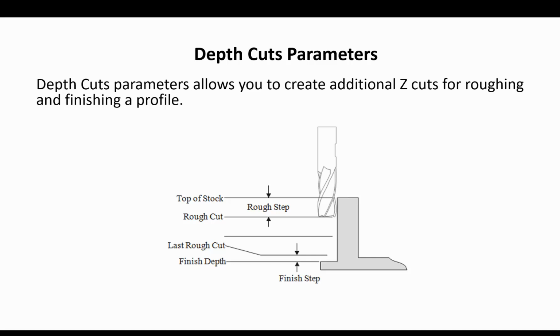Hi everyone, in this video I'm going to explain the depth of cuts parameters that allow you to create additional Z cuts for roughing and finishing a profile. The depth of cuts parameters that I'm explaining are from the contour toolpath, but most of the parameters are going to be available in all the other mill and router toolpaths.